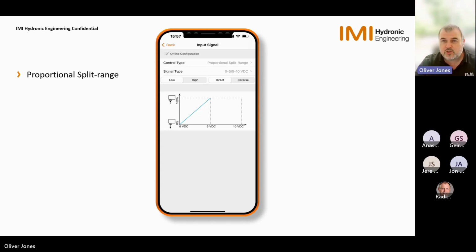This does halve the control. So you do affect the amount of control and the controllability across the valve. But it's a finite point that you might want to look at. It depends on how critical you really want it to be. And of course, the most critical point is that we're still controlling at this low end. And even with splitting the voltages, we can still control to low flows for 80% of the year, where we're actually only at 20% of the flow.